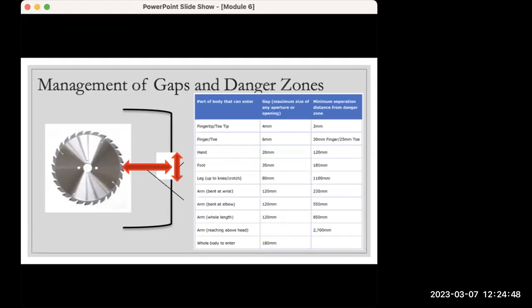This allowed a person to squeeze between the wall and the light curtain, bypassing the light curtain and therefore it was no longer effective. I've also seen examples of light curtains where a person is able to reach over the top of the light curtain and come into contact with the danger zone, or go under the light curtain and come up into the danger zone as well.